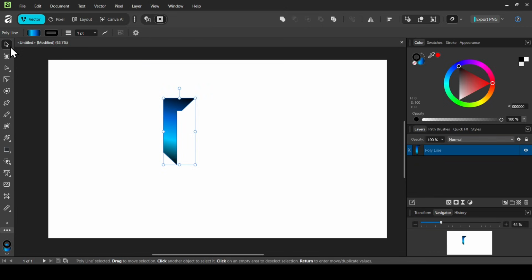So now let's select the move tool. So now click on the gear icon here. Check the enable transform origin. So this is the transform origin. So I'm going to move this circle here to the center. So I'm going to move it here, move it to the right. So as you can see, it snaps. And then I'm going to move it down until it snaps here. So here it is. It is in the center of our canvas.